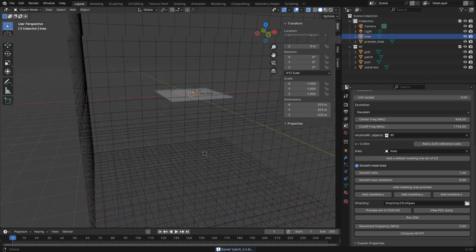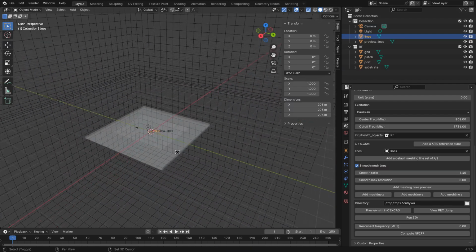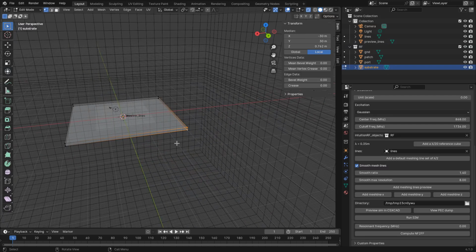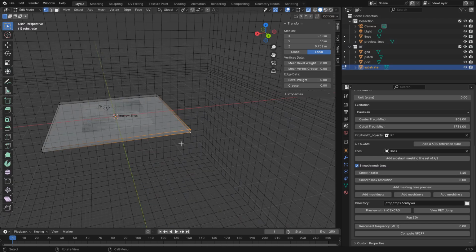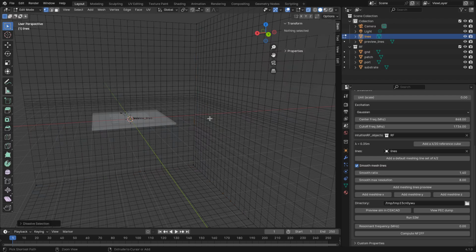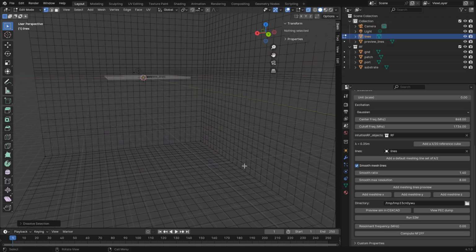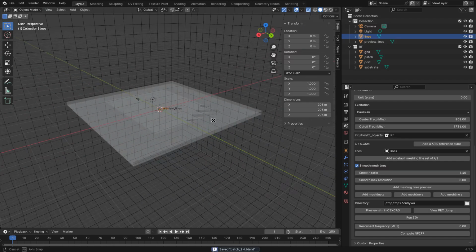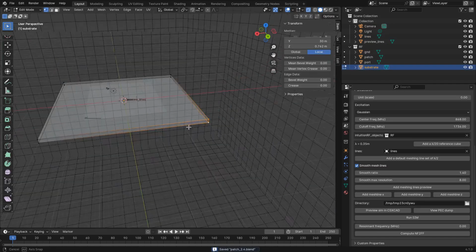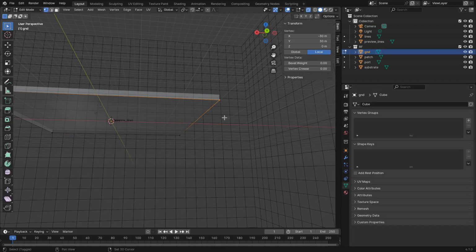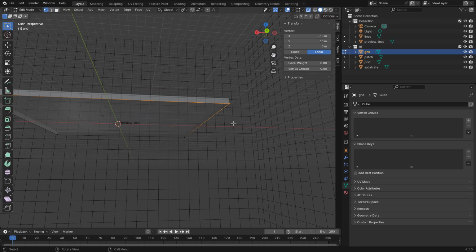This, however, is not the best option for our case because when we decide to change the geometry of the antenna, the meshing lines won't move with it. So what we can do instead is remove the vertices we added like this. You see the meshing lines are back to normal, and now what we can do is create vertex groups on the objects and assign anchors for IntuitionRF to use as meshing lines.